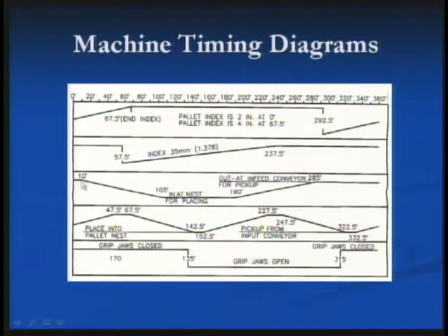The thing I'm interested in most is the assembly motions or other kinds of motions that are being created on the machine with the cam systems. This represents one of them. You see a dwell at a high position for about 10 degrees, a fall to 105 degrees. It says it's now in at the nest for placing a part. It stays there until 190 degrees. It comes back out at 285 and dwells at the out position. So this would be a double dwell type motion as described in your book.